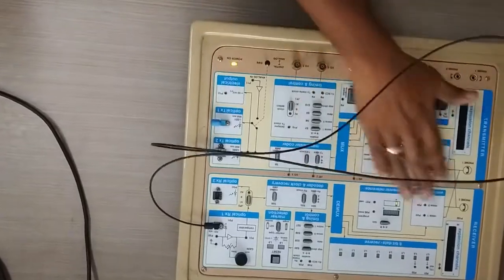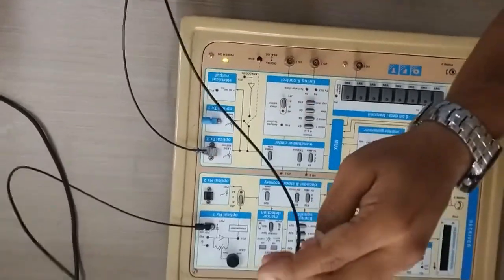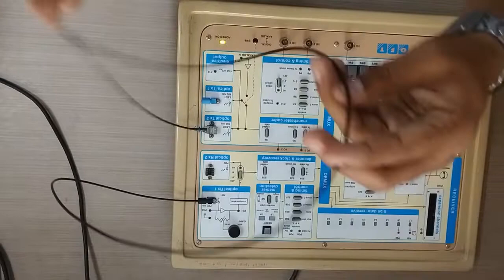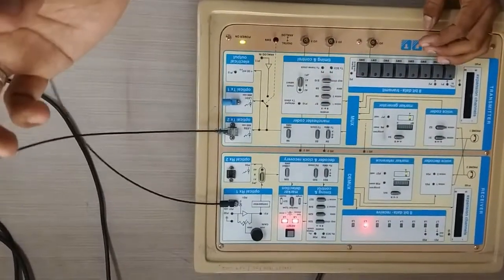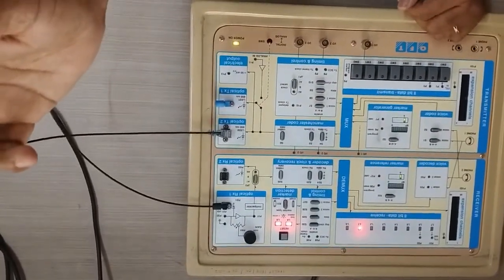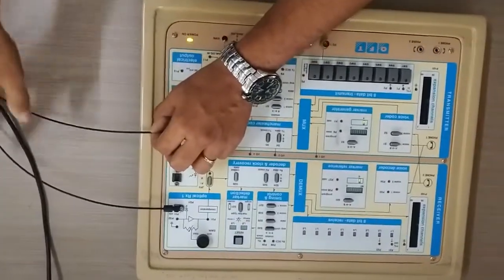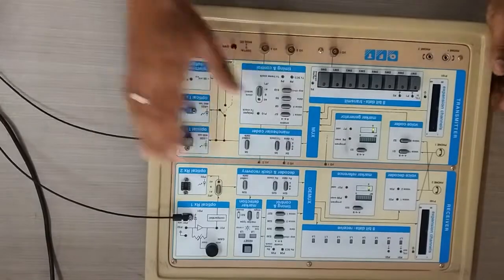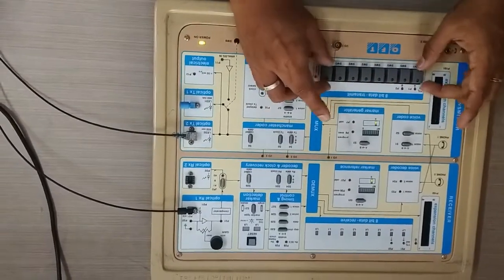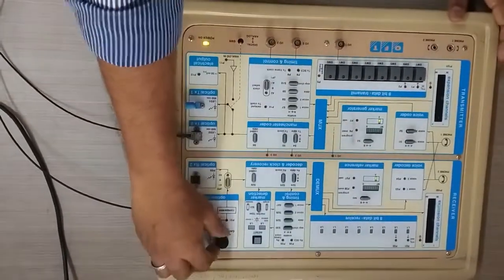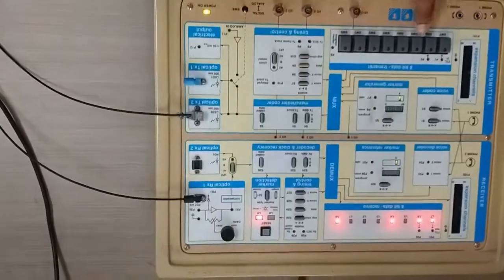We have a transmitter section, receiver section. We have connected the transmitter and receiver section with the optical fiber cable, 1 meter cable, and this is a multimode fiber as we discussed. Okay, and we are using 650 nanometer range. Okay, so what we have to do is we have to verify whether this 8 bit of data is transmitted to the receiver section, and I am going to change the gain.